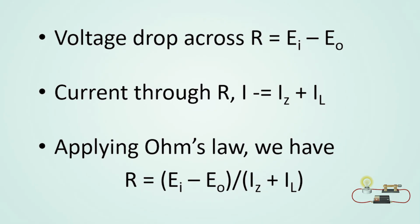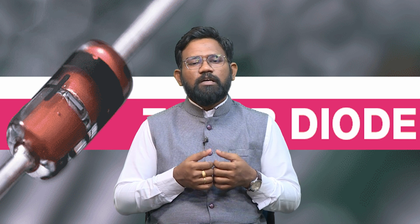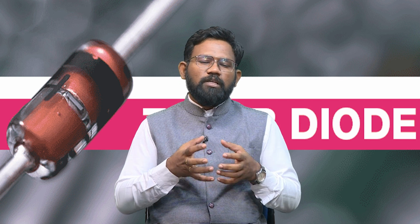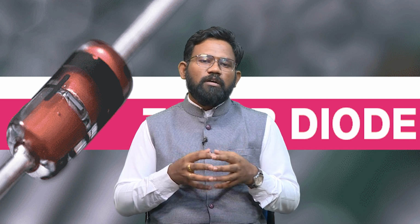Now, the voltage drop across R will be equal to Ei minus E naught, that is the input voltage minus the output voltage, that will be the drop across the resistance R, and the current through R will be equal to Iz plus IL. That means the current flowing through R will be the summation of Iz plus IL. So, applying Ohm's law, we get the value of resistance equal to Ei minus E naught divided by Iz plus IL. So, this will be the value of the series resistance connected in the voltage regulator circuit.